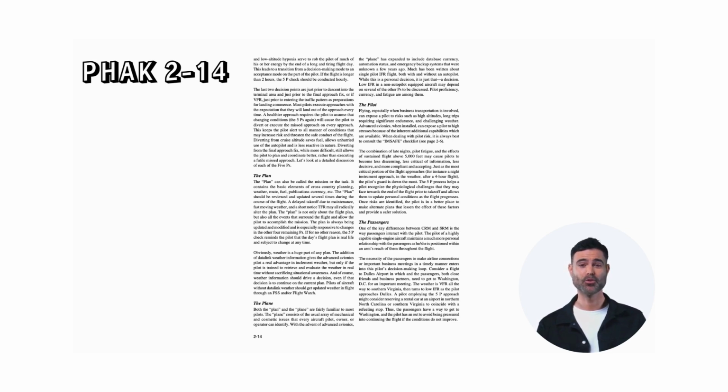Obviously, weather is a huge part of any plan. The addition of data link weather information gives the advanced avionics pilot a real advantage in inclement weather, but only if the pilot is trained to retrieve and evaluate the weather in real time without sacrificing situational awareness. And of course, weather information should drive a decision, even if that decision is to continue on the current plan. Pilots of aircraft without data link weather should get updated weather in flight through an FSS and/or flight watch.